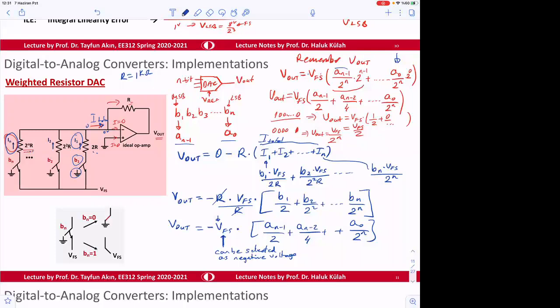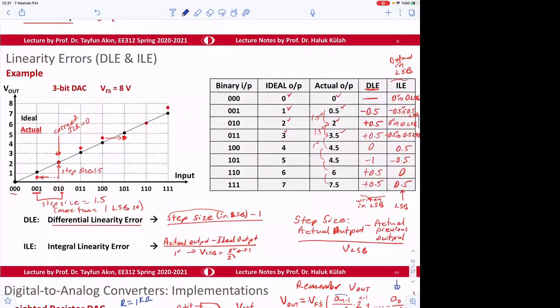For 10-bit, it's supposed to be 1.24 mega ohm. So is it going to be with that precision? Any mistake in those resistances is going to be creating an error. That error will be causing us these mistakes here. So that's the basics for the errors also.